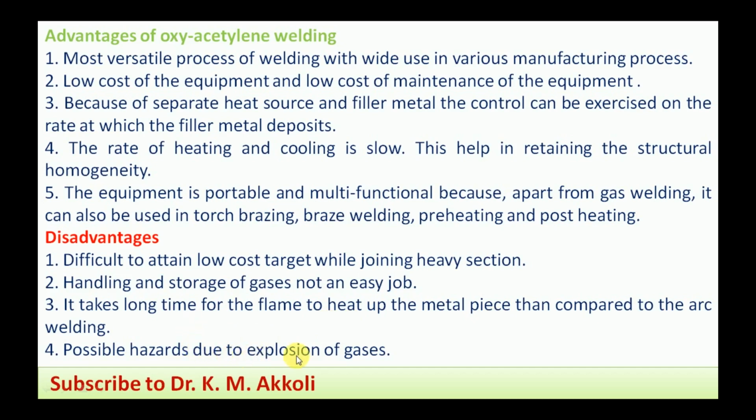And there are possible hazards due to explosion of gases. As we know, acetylene can combine easily with oxygen or atmospheric air and get combusted. If any leakage of the gases catches fire, the cylinders may explode, and that's why explosion hazards will be there. Care should be taken regarding leakage of any gases. Those are the different disadvantages associated with oxy-acetylene welding.